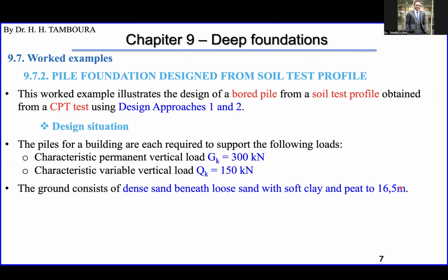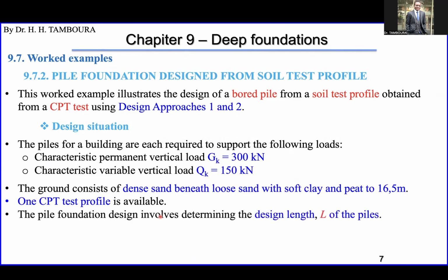Okay, so we are now describing the soil layers, and we have one CPT test profile, which is really not enough for a very important project. You need more than that. But anyway, we are going to do with it. So only one is available. Okay.